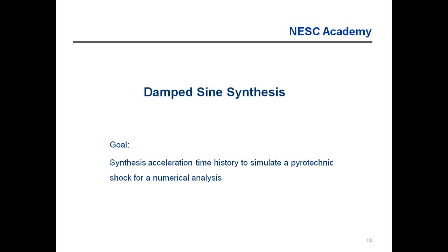Anyways, we do end up enveloping our measurements, and then we add margin on top of that. So the specification that we actually take into the test lab is much more conservative than the SRS from our actual measurement. But the goal here is to come up with a plausible time history that matches that SRS, and then that time history could be used, say, for a base input for a modal transient finite element analysis.